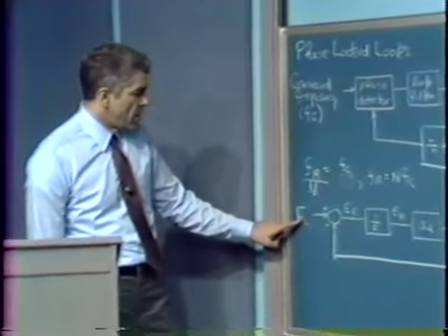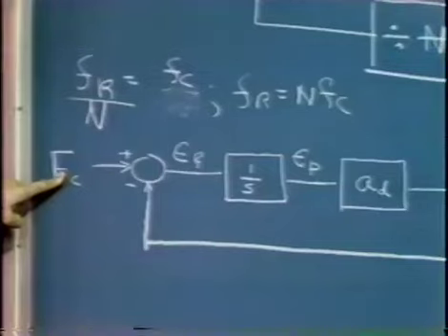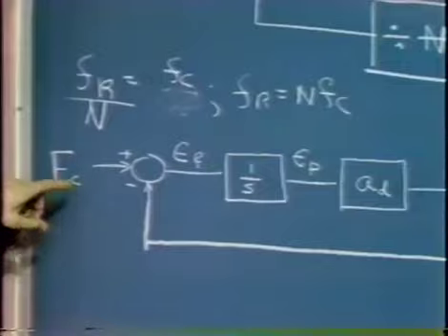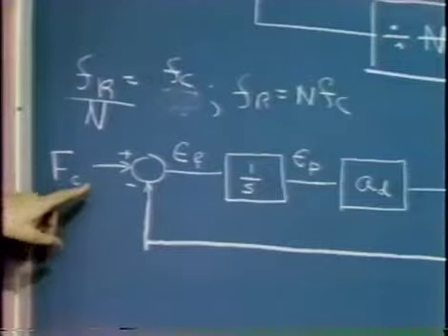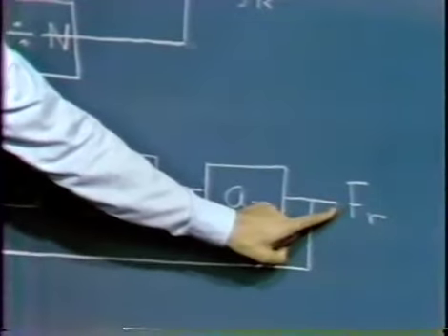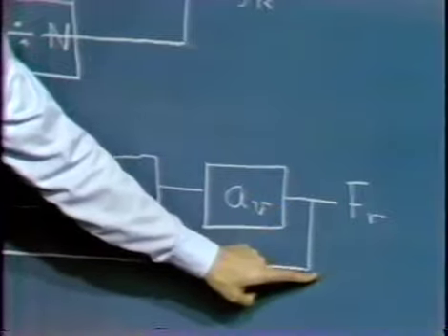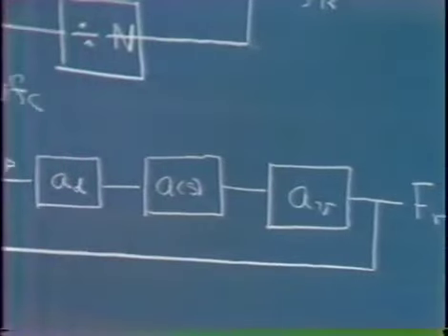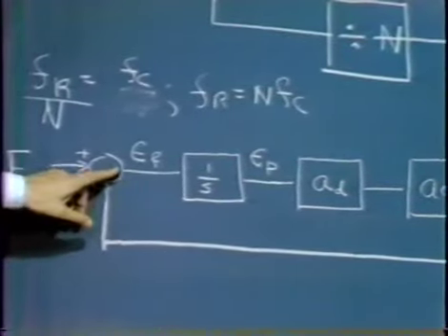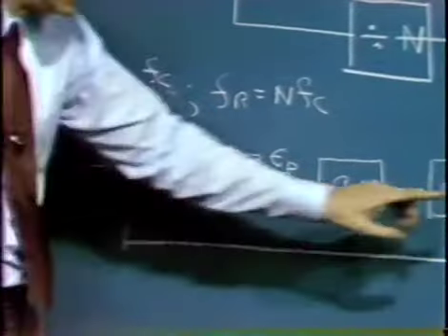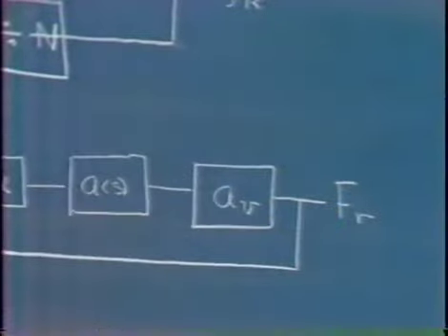And when we do that, we end up with a linearized block diagram that's something like this. We have our commanded frequency at the input. Again, I'm using linear notation or frequency domain notation here, the capital F sub lowercase c, as the input to our system. And the system responds, the transform of the linearized output is capital F sub lowercase r. And we subtract those two quantities. The resultant difference is the error in frequency between the command signal and the signal being provided by the phase-locked loop.